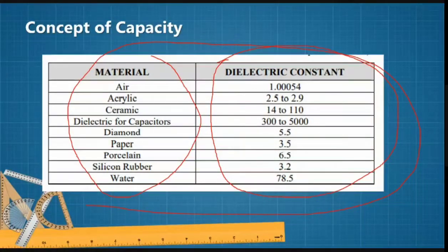The dependence on frequency is because the dipoles must reorient themselves in each period of the applied voltage, because the applied electric field inverts its direction. Different crystalline structures of the dielectric make that reorientation easier or more difficult.